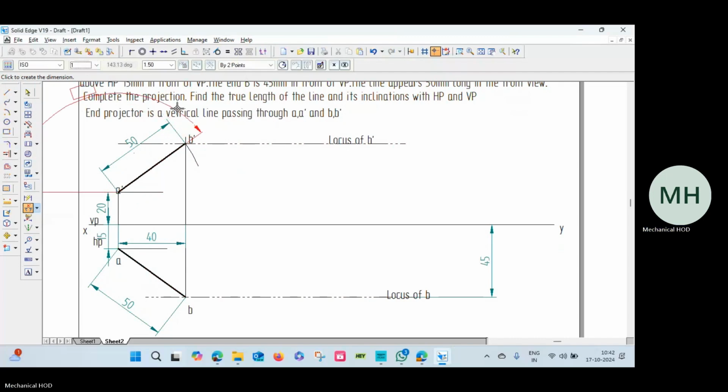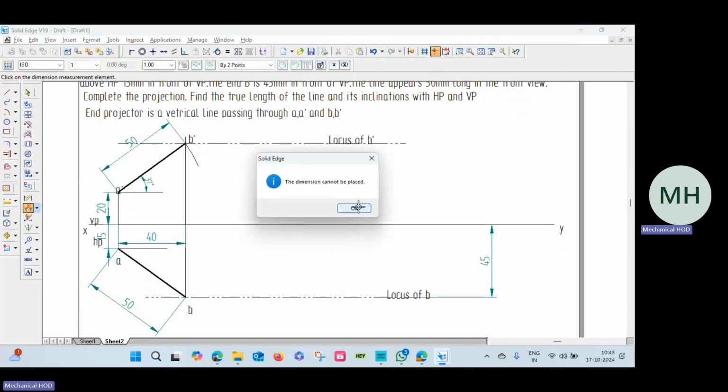Okay, let me change it to 1. It's very big. Let me change it to 1. 37 degrees. Similarly, find the angle between this line and this line with the angle between command. Select it and click on this line and click on the other line. It will show both are 37 degrees.